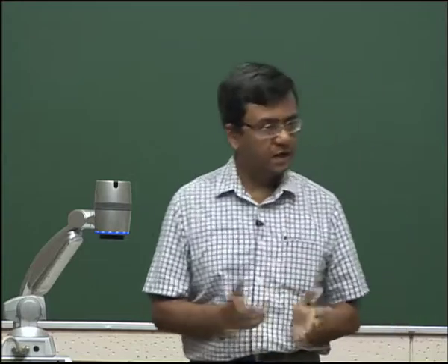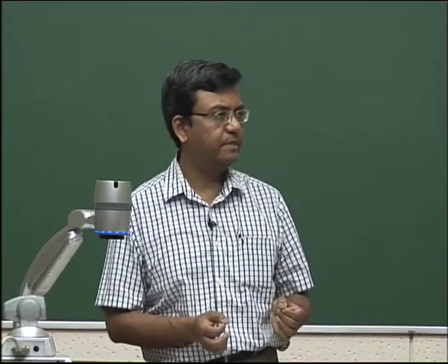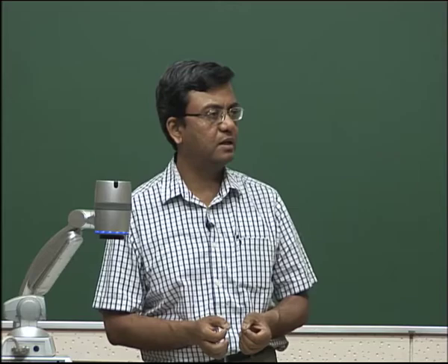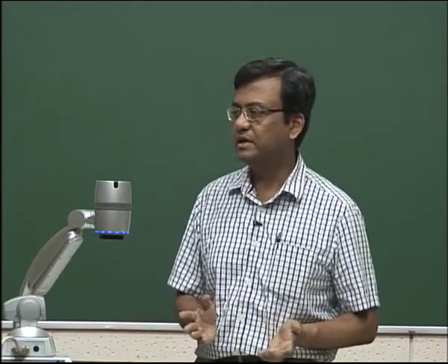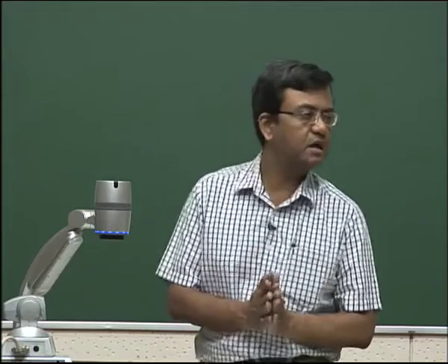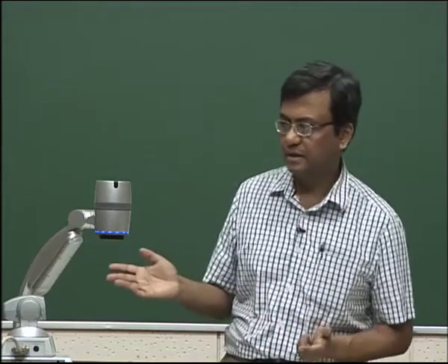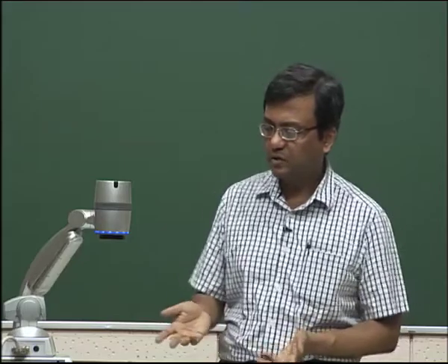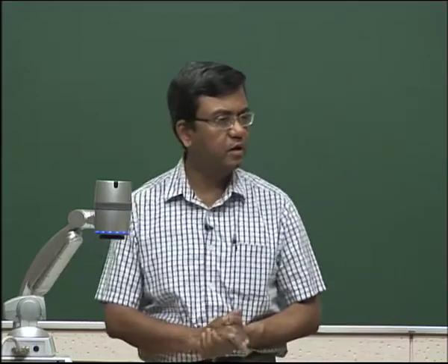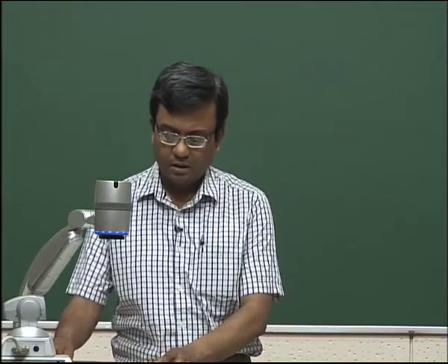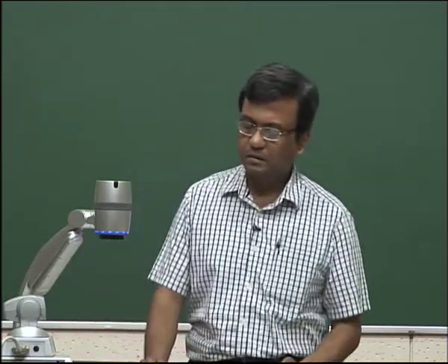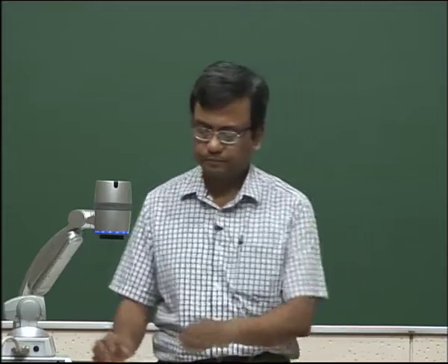But for the spherical situation, we just picked up the Shvab-Zeldovich equation from the book and used that to get the energy equation, and simply integrated this between the droplet surface, that is r equal to r_s, and r going to infinity. And from that we essentially got what we wanted. We got m dot, and we also got the d square law and the droplet lifetime.